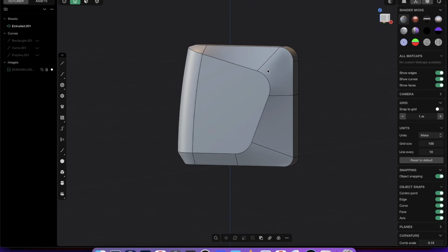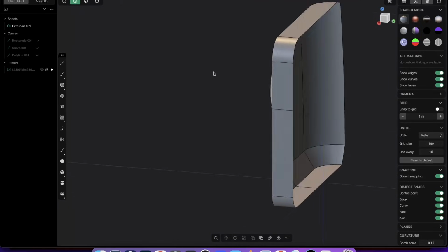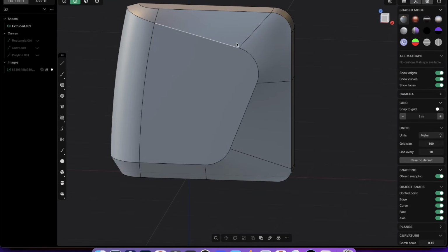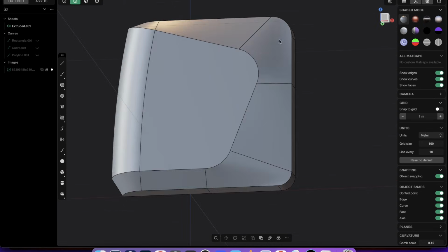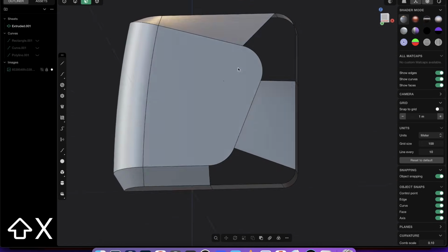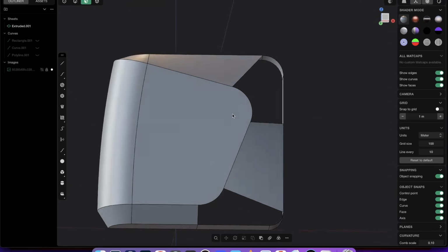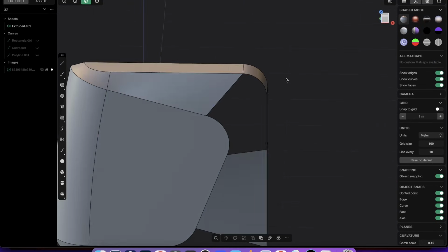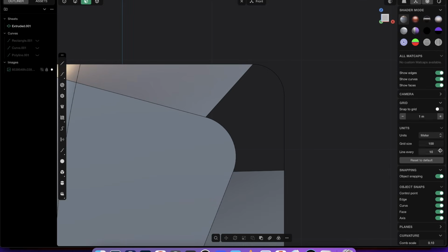So again, there are thousands of different techniques and you can spend so much time to do it perfectly, also with square, but it's way too advanced. If you render that later with the material, you will anyway not really see that. But let's select those faces, Shift X, delete them. And focus on this one first. So I want to cut here a piece away. So I want to delete this.